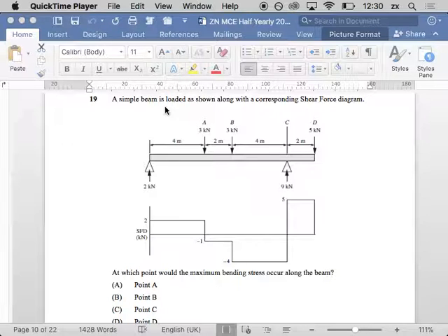What I need to do is I need to find out how do I get from 8 to this 10. Okay, so let's tell the story of some areas. Once upon a time there was this area and it had 8 kilonewton meters in it. And then it came along to another block. And this block was -1 below the line. And how wide was it? It was only 2 meters wide. So the value of that block was 2 times -1, -2 kilonewton meters. So the value that was originally 8, it now lost 2, and it was now 8 minus 2, which is 6.